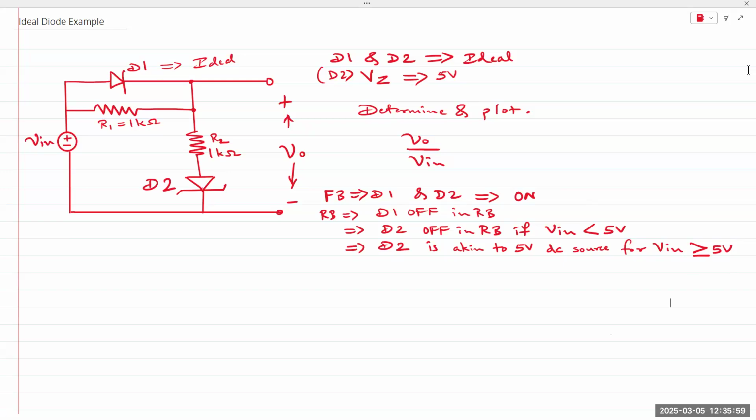Yes. So the question being asked is if there was a resistor in series with which one? There will still be R2. You can add it to R2. So if there's a resistor here, electrically speaking, it doesn't matter where you connect that resistor as long as it's in series. It could be a 100 kilo ohm resistor. You add it to R2, it becomes 101 kilo ohms. Schematically, we can say it's before or after the Zener. But electrically speaking, when you take the equivalent circuit, it doesn't matter where it's connected.